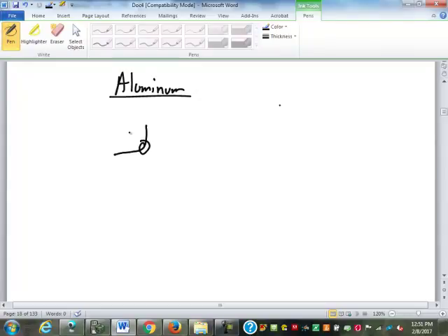And when they rearrange, a metal is a crystalline lattice, and that lattice is perfect. And the more perfect that lattice is, the softer the metal is. Well, every time you bend it or smash it or stretch it, that lattice gets imperfections in it. Well, those imperfections actually make it stronger, but they also make it harder. So when you're bending that wire back and forth, you're creating imperfections, and the imperfections stack up until it gets so hard that when you bend it, it just snaps there.